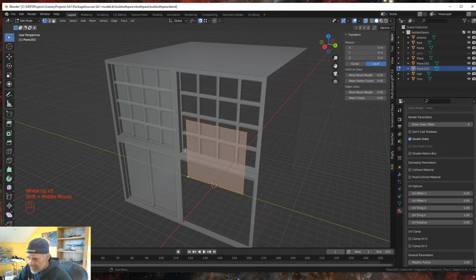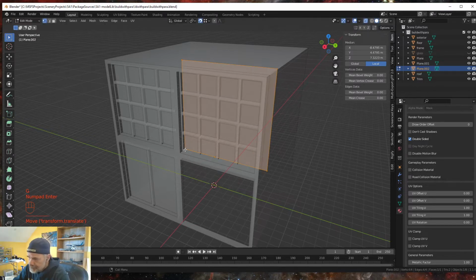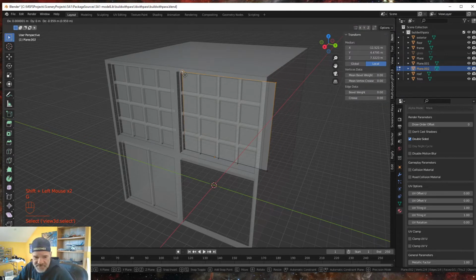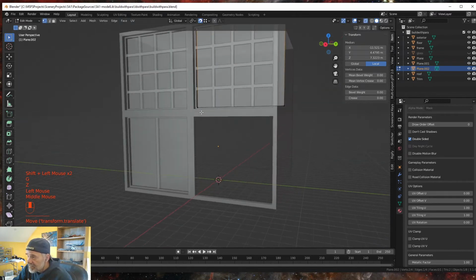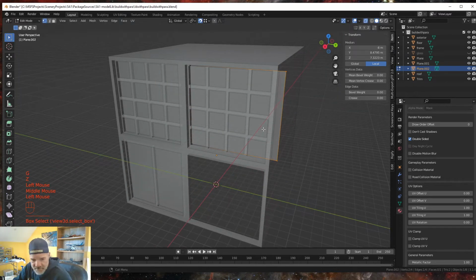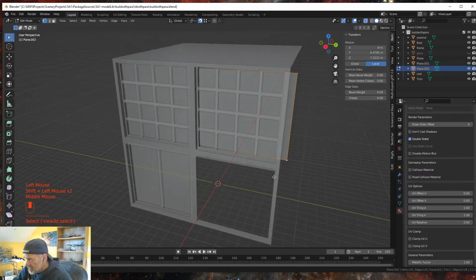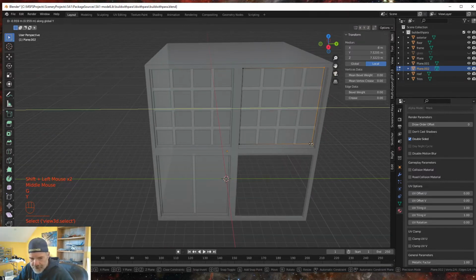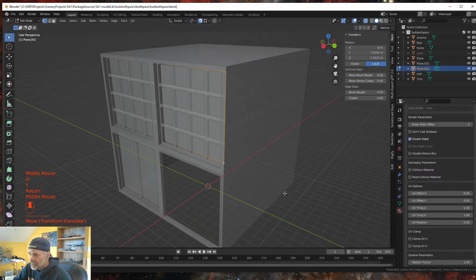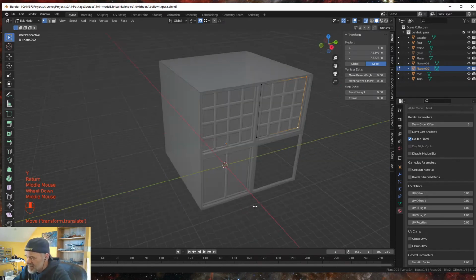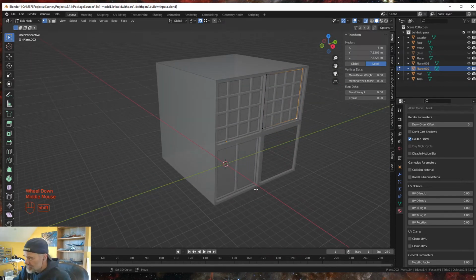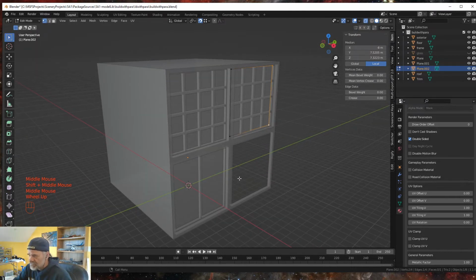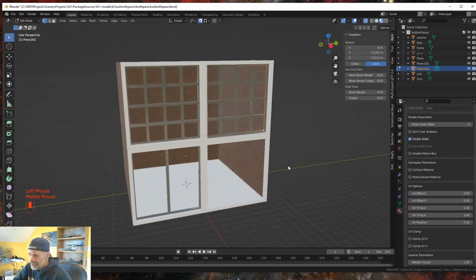So I'm going to hover my mouse at that corner, hit G, and then size it again just like we did before with the other ones. And we're going to GZ till down there. That looks good. Over here, lower right hand corner, we'll move that GY. Okay, so that room is right there. Now, when I bring it into the sim, I can't remember which way that room was oriented.